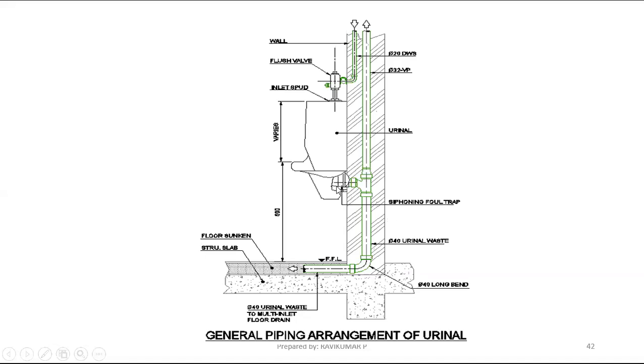After the floor drop, we are taking a 40 mm pipe here. The drain pipe we are taking at the bottom. It will be connecting into the floor drain. After this, it is going upwards with the reducer, 30 mm. We put a 30 mm reducer for the 30 mm vent pipe. The vent pipe is going to the top only.